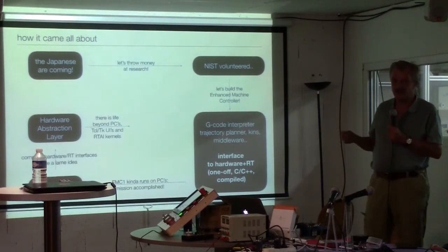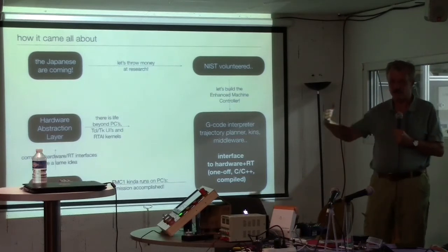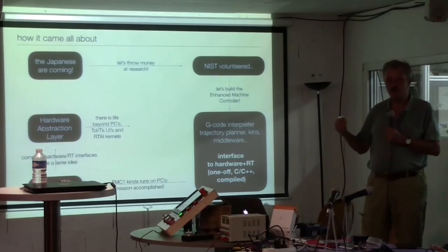And in particular, since we're driving hardware at very high rates, a kilohertz and up, we cannot get by with a standard Linux kernel because those do not react in time. Those have latencies sometimes in the milliseconds range. We need what's called real-time patches for the kernel.